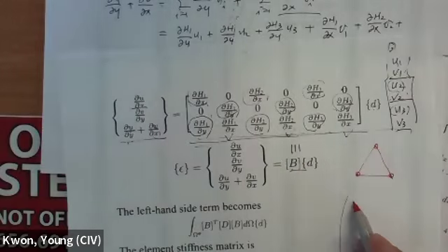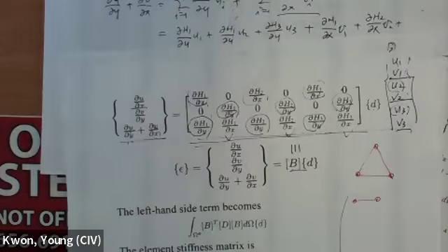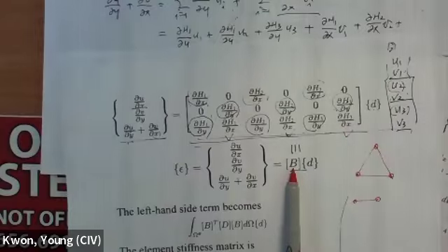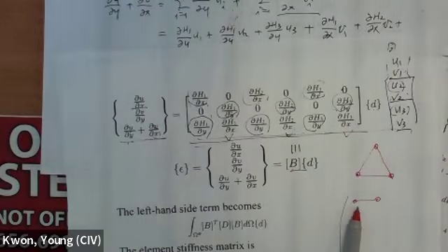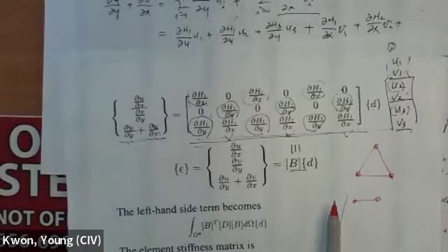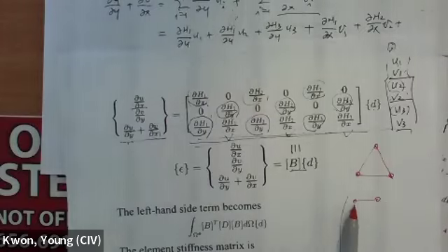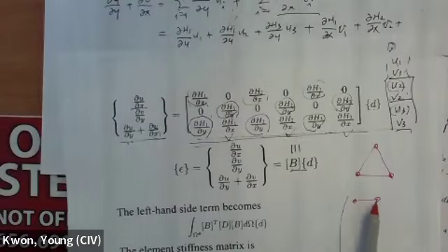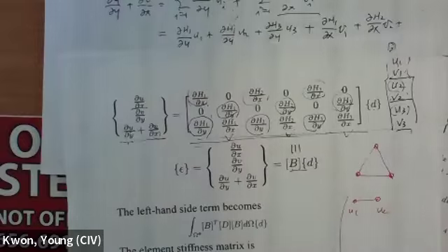If I use a 1D problem, like that one, then what is this matrix B going to be? 1D problem, so 1 by how many degrees of freedom? 2 nodes, each node has a single degree of freedom, so this is U1 and U2. So that's going to be 1 by 2. All right.